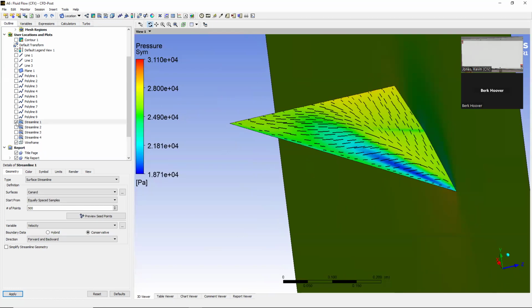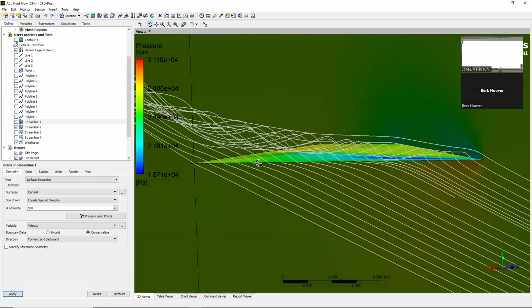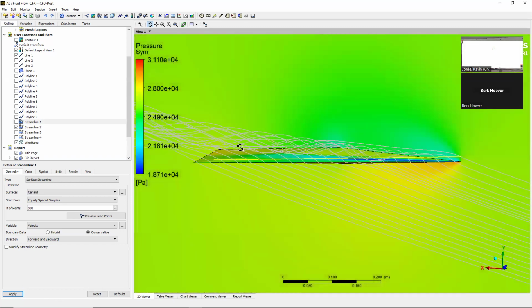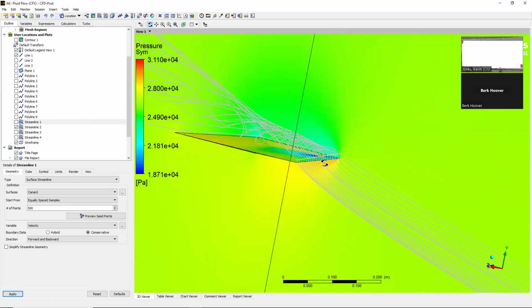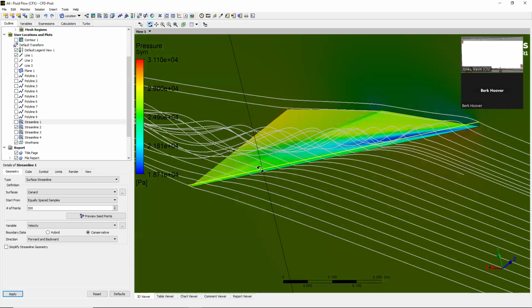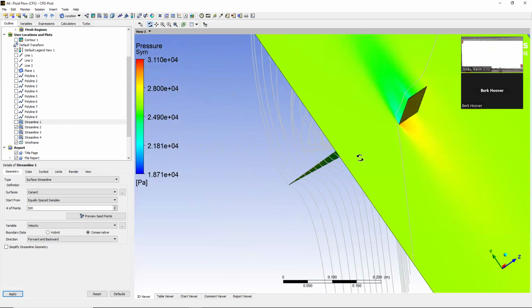Let's see, and then you can do exterior streamlines. So here's some streamlines that were seeded just high enough. That's where they were fed in. So I basically put in a line that was just a short distance above the leading edge of the wing as the seed point. And so they're pretty good at showing you the spin up of that vortex.